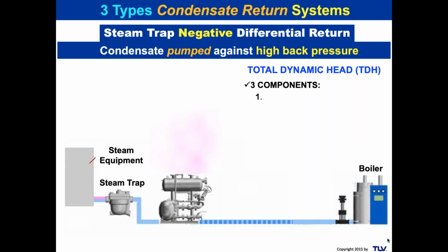That's three components. It's the vertical lift into the return header, or to the flash vessel, or both. It's the piping frictional loss along the way, and it's the destination vessel pressure. Sometimes the flash drum, knockout drum, flash vessel, they have a positive pressure because they're doing flash recovery. So we've got to add those three components up. That's the TDH. People just say the back pressure.